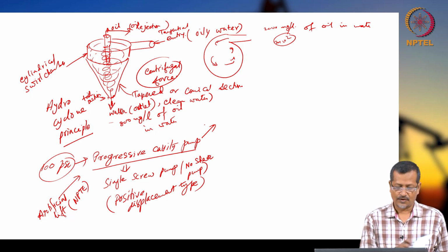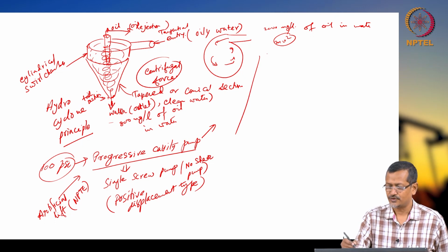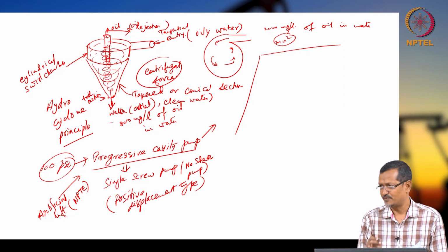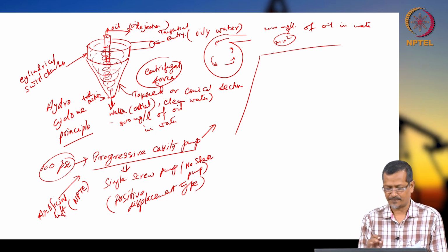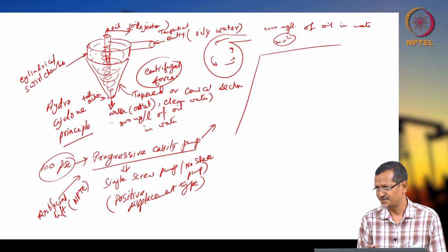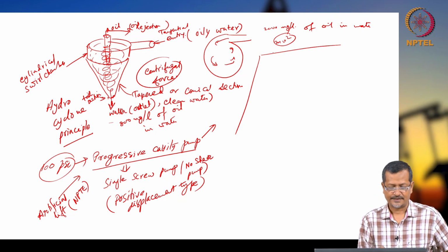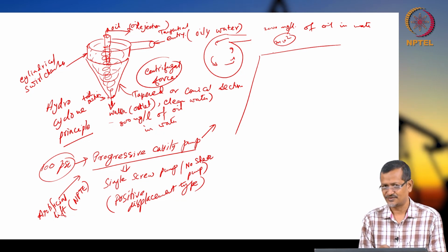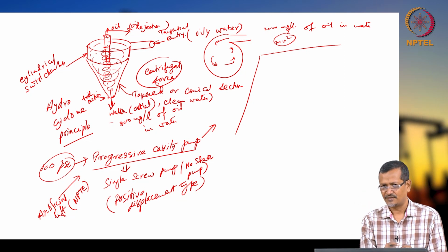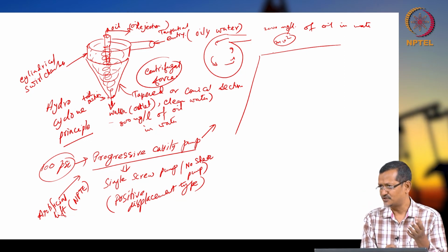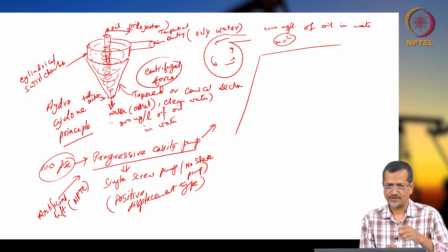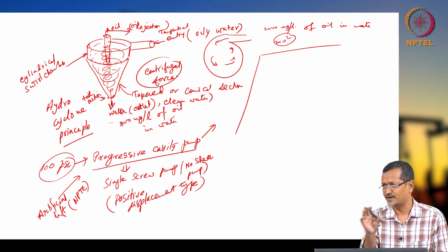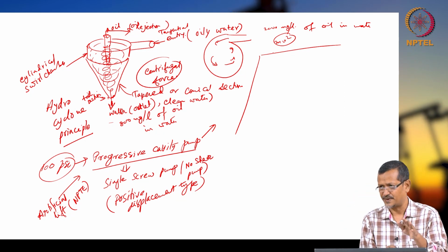Now, this hydrocyclone has advantages. There is no moving part, so minimum maintenance and operation is possible. Then the compact design reduces weight and space requirement. It is just giving rotation. For example, a flotation chamber with dissolved gas or dispersed gas will take larger space, but a hydrocyclone system is very small and compact. So it will not take a lot of deck space.